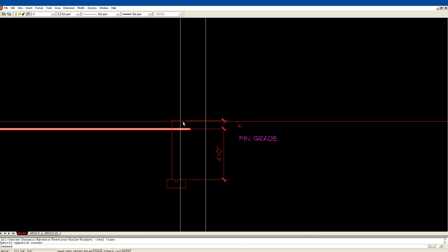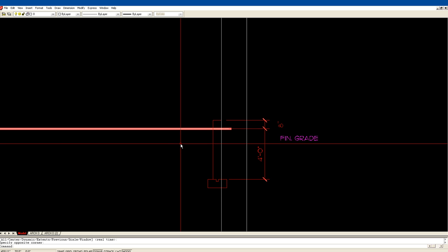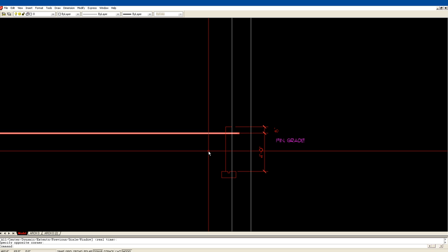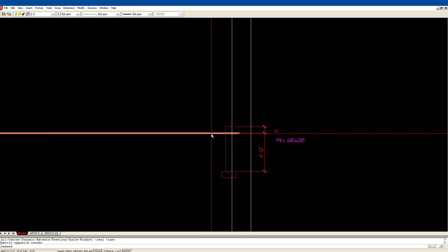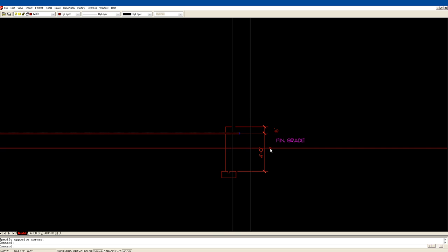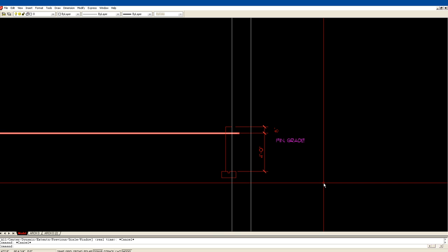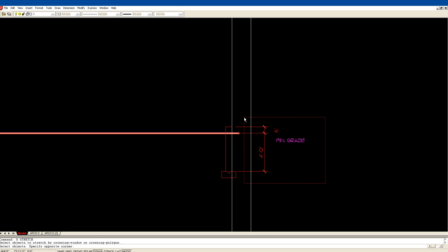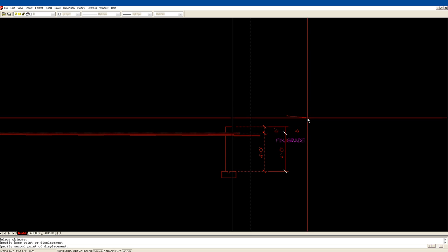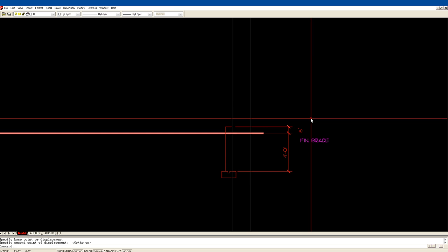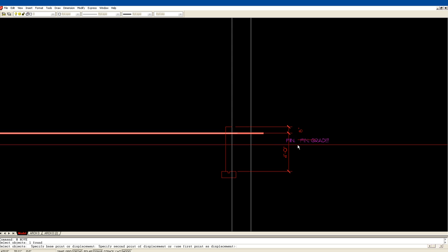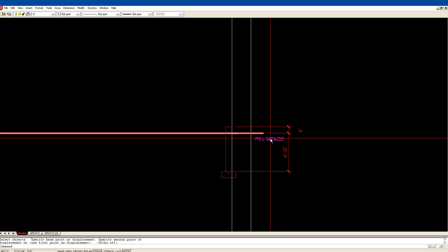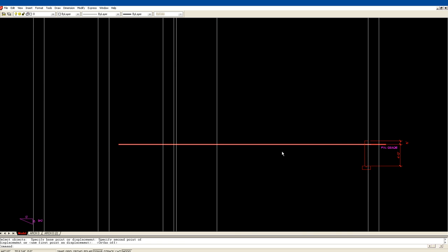Okay, so what this says is that the top of my foundation is 8 inches above my finished grade. This is my finished grade. This heavy line that you see here, I'm saying that that's my lawn. That's my front lawn. Okay, that's my finished grade. You can just click on it and actually you can stretch. We can do this. And just bring it out more. Oh, we want ortho on. Okay, we can move this to somewhere where it makes more sense. There.